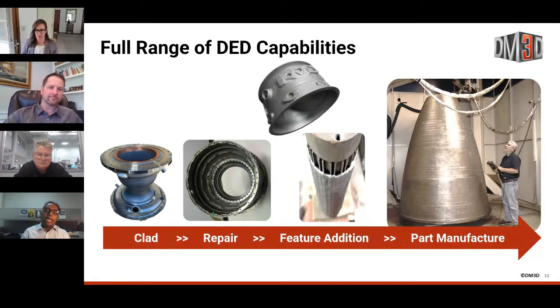And that's where, again, simulation may be very handy, but what's extremely important is process control, and we use our closed loop process control for that, minimizing the heat input to that area and building it back with dimensional integrity, because it's a finished part. There is no stock material anywhere, and you cannot afford to distort it anymore. So these are two unique situations of repair, and both have their own challenges. But DED is a unique tool to do this.